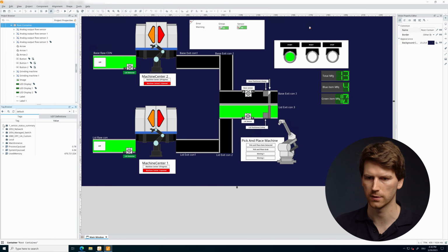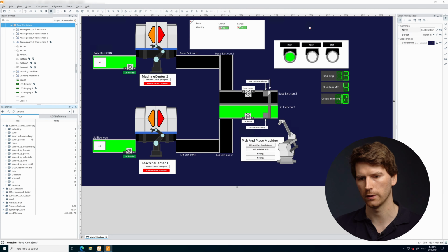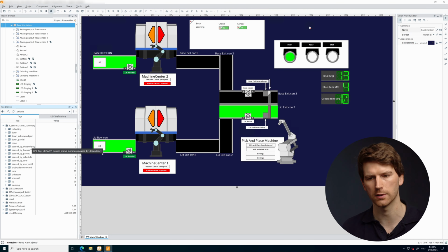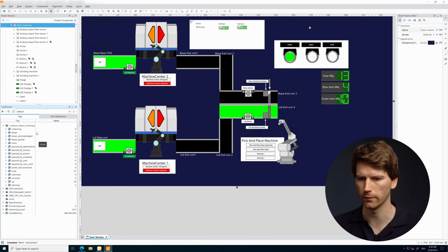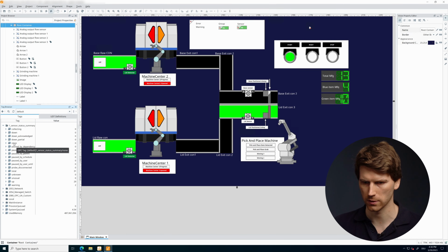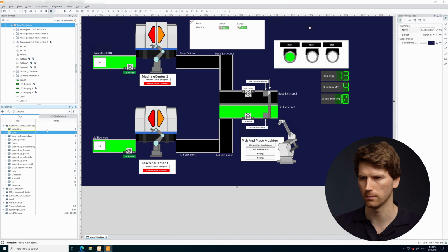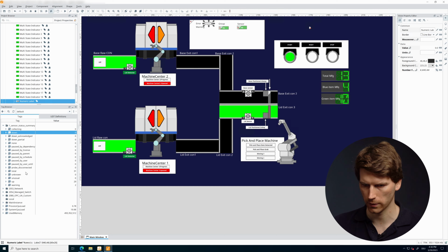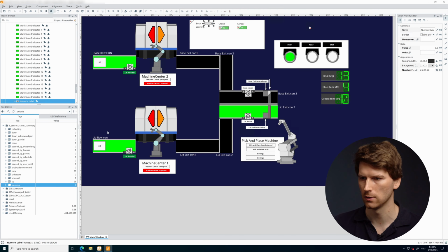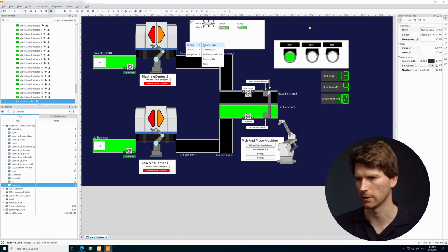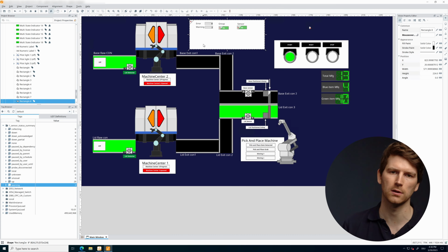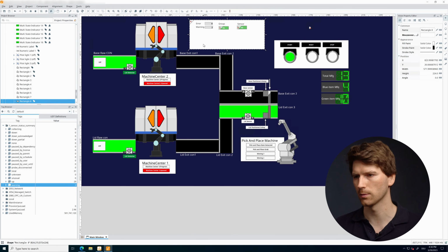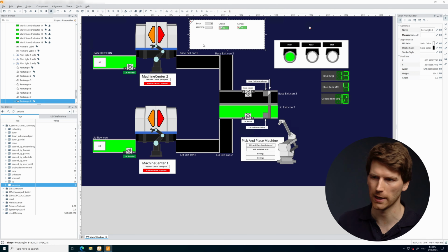And as you can see, we have the sensor status summary. So that's all the information about how many sensors are currently in down state, up state, warning state for a more general overview. And we can simply do that by just selecting how many sensors are currently down. We don't have one, but I just drag it in here and say, please display that as a numeric value. And then we can move it in here. And if we go to warning state, then we have currently 2 sensors. So I just drag it in here, display again numeric label, and then we currently see that we have 2 sensors in our PRTG installation in warning state. But that's not very descriptive, so they just know there's something going on, but not actually what is actually happening.